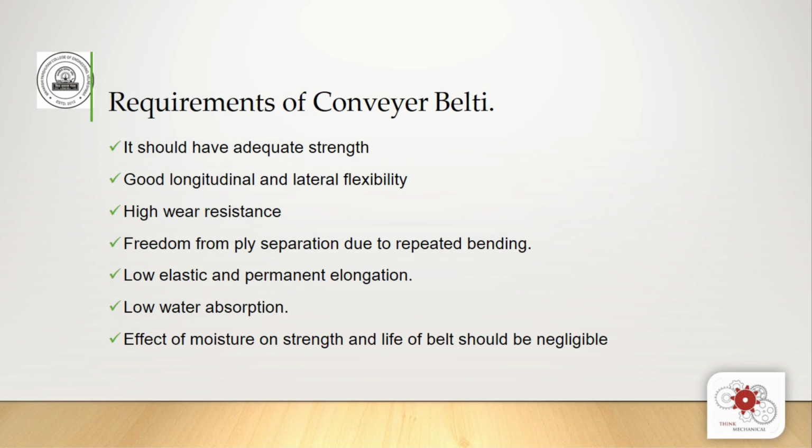Then what are the different requirements of belts? The belt requirements are: it should have adequate length, good longitudinal and lateral flexibility, high wear resistance, freedom from ply separation due to repeated bending, then the belt should be low elastic and have low permanent elongation.